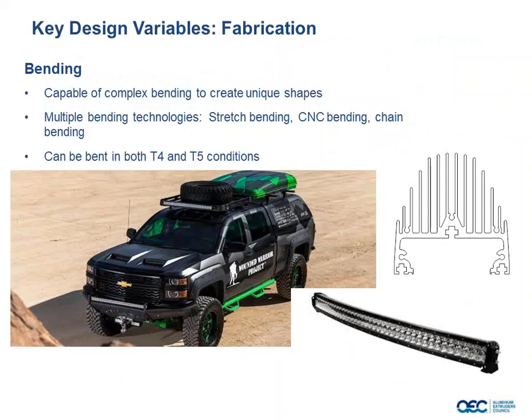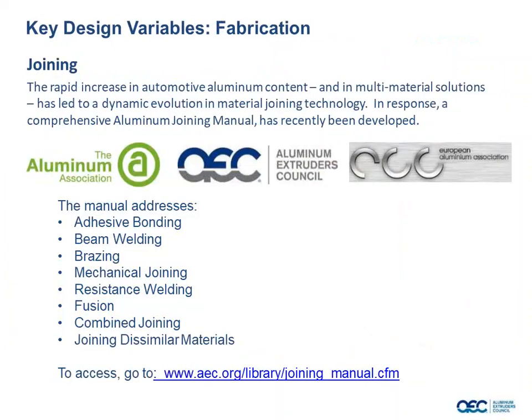As an example of just some of the capabilities, here's an example of an LED light bar for an off-the-road vehicle. This one is a fairly tame extrusion, meaning it's extrudable. But the hard thing is the bending, and can you form that, and we call it the wrong way or the hard way, but that's what the application needs. So a great application for bending concepts. So I would encourage you to think it just doesn't have to be a straight part. It can be formed in many different planes, and there are great processes to do that.